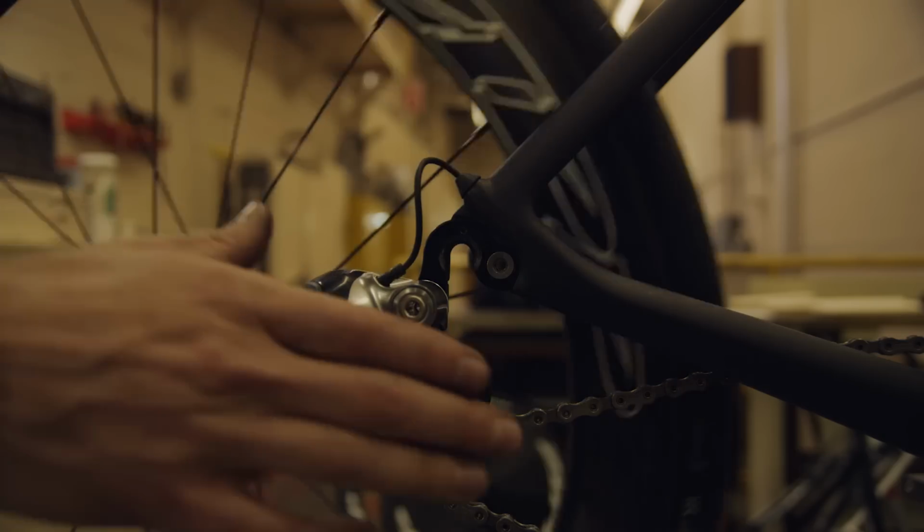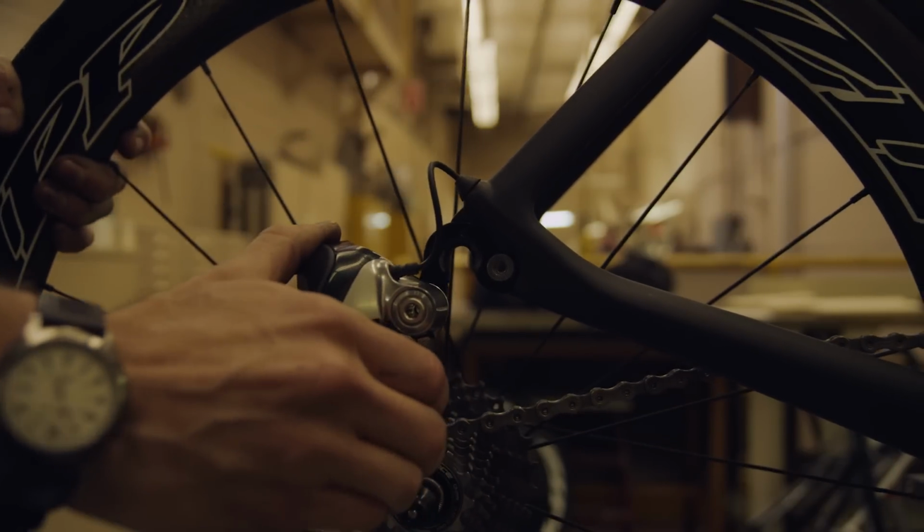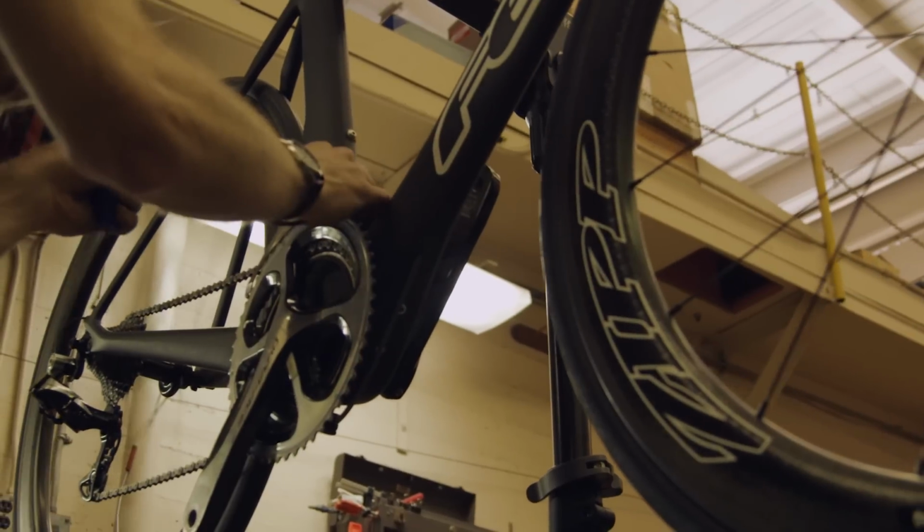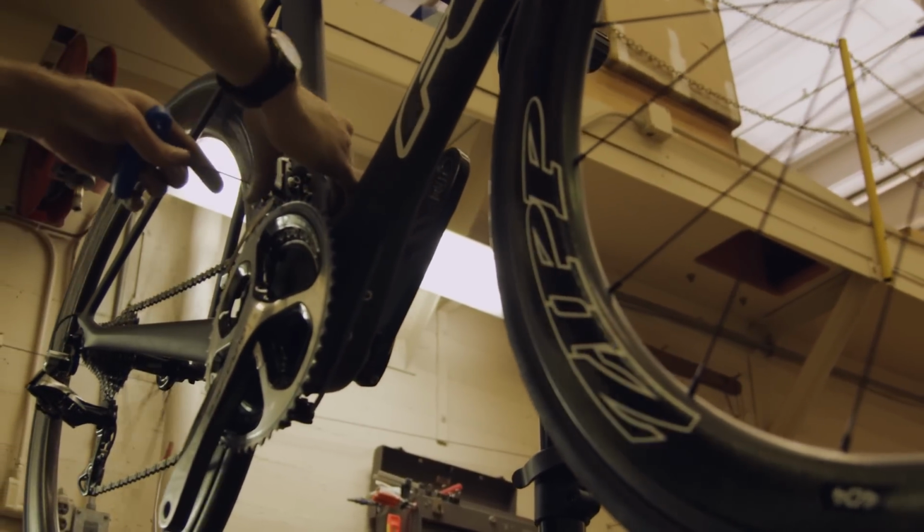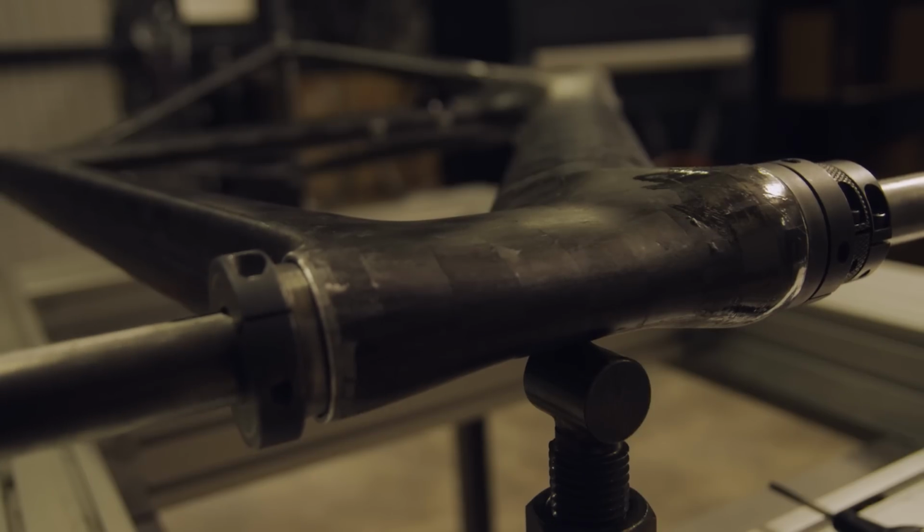Once everything is tuned, we'll go to the factory and start working in carbon fiber, and there's another process of tuning the ride characteristics and the weight and the stiffness with that carbon layout. When that first prototype comes back, that's the best part. You finally get to put parts on it and ride it and make sure that the geo you decided on really does function as you intended, and the stiffness numbers are really matching up on the table to your FEA, and then you start working on the next few sizes.